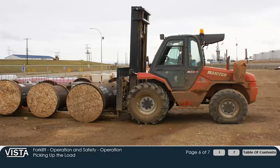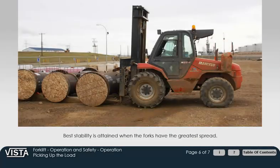To pick up the load, place the forks as far under the load as possible. The space between the forks can be adjusted. Best stability is attained when the forks have the greatest spread. On some forklifts, this can be done hydraulically from the operator's seat. Level the forks before sliding them under the load. It is better to have the fork tips pointed slightly down rather than slightly up because of the possibility of damaging the underside of the load.